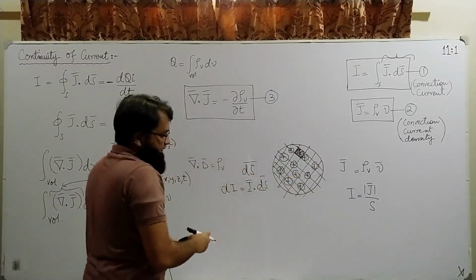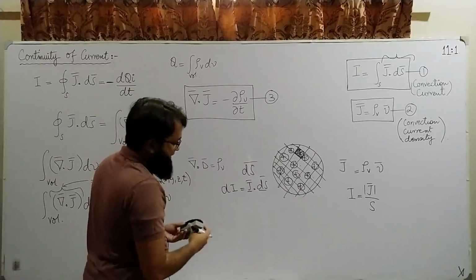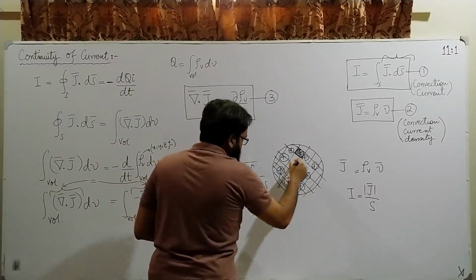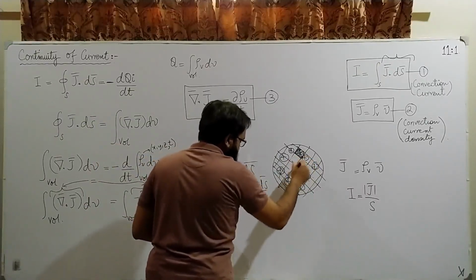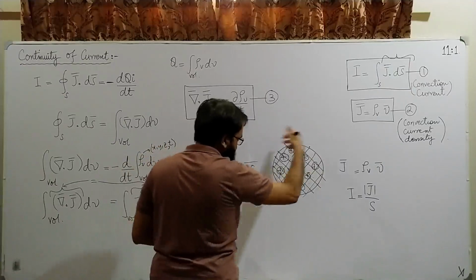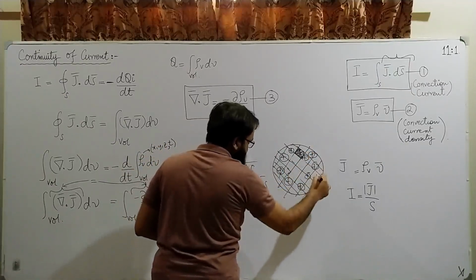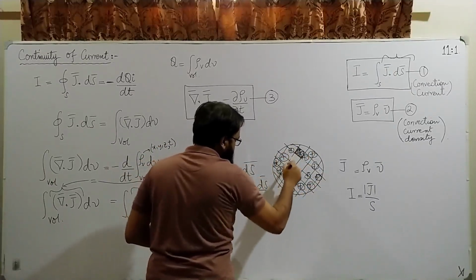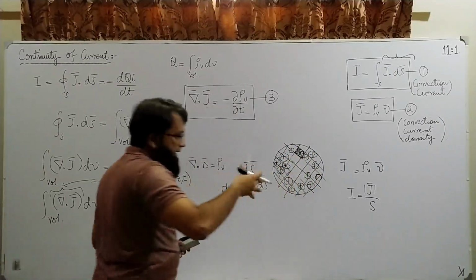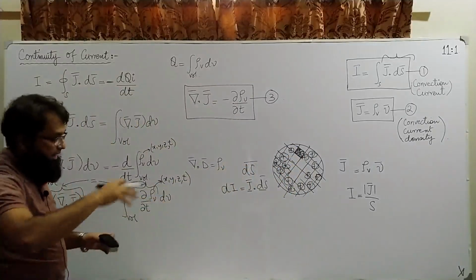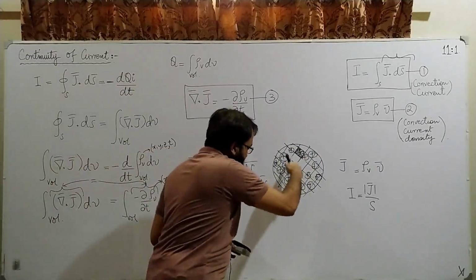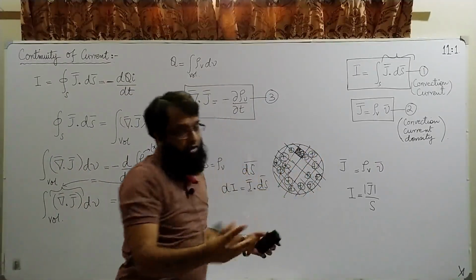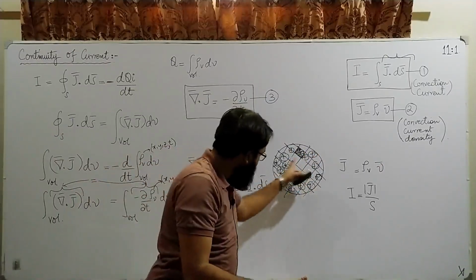In the AC case, alternating current, where there is some frequency, the current distribution changes, and it gets concentrated on the surface of the conductor, and in the middle the charge density becomes very small, and as you increase the frequency, the availability of charges, in other words the charge density at the center, reduces.